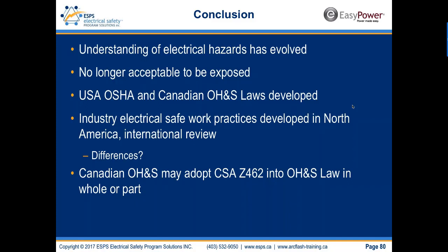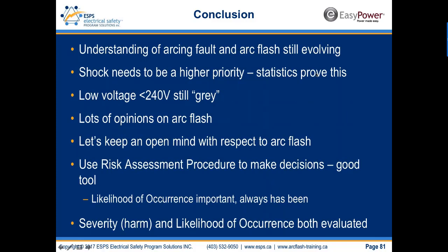There's international changes, and they aren't necessarily using 70E, so we have to manage those and understand the difference of opinions between Europe and Australia. In Canada, OH&S laws may adopt Z462 in whole or part into law. Our understanding of arcing fault and arc flash is still evolving. Shock needs to be a higher priority. Statistics prove this. Low voltage, less than 240 volts is still a gray area.